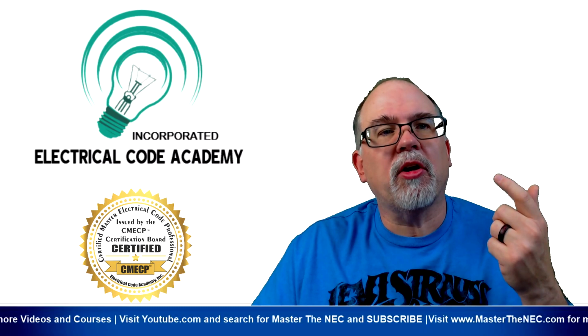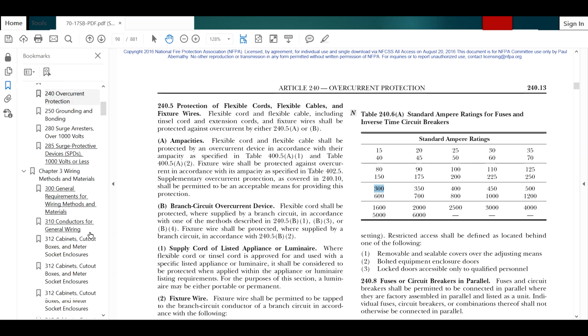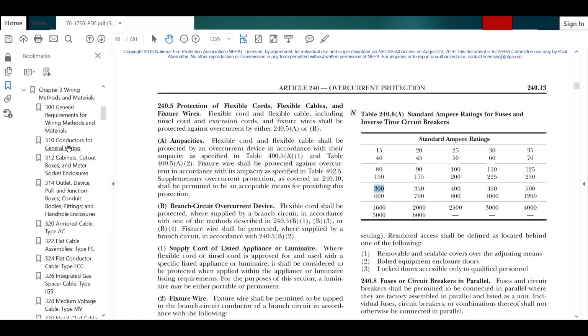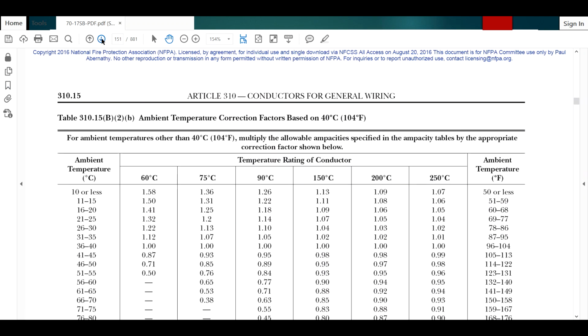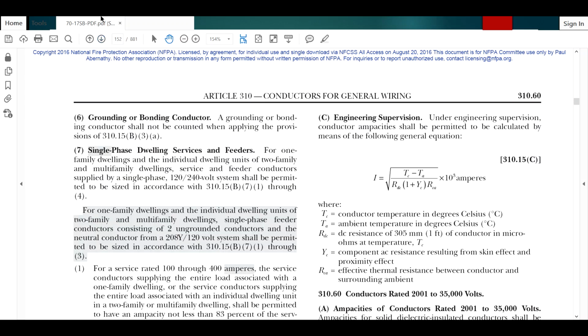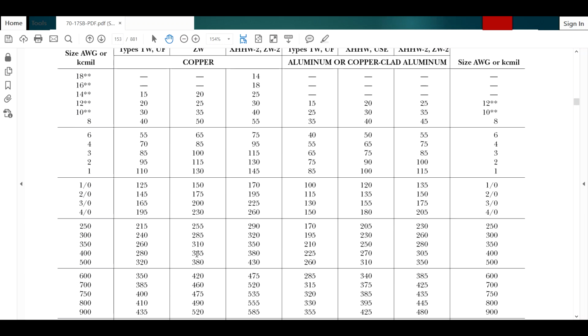All right, so we're going to go to the NEC and simply find a conductor. We're going to go to 310.15(B)(16) again. All other things being considered, 75-degree rated terminals, nothing changed there. We're still using THHN, THWN-2. So what we're going to do here is find something that's going to handle 300 amperes. It looks to me like we could use a 350 kcmil. And remember, copper unless expressed otherwise. In your exam, always assume copper. Of course, you could do aluminum in the real world, but whatever's on the exam, assume copper.